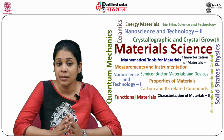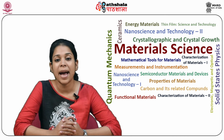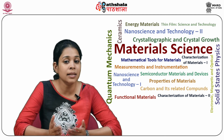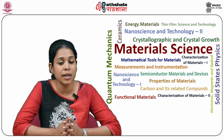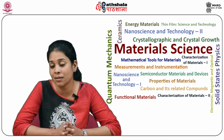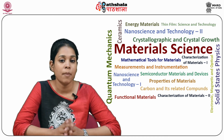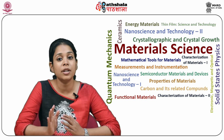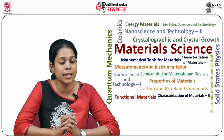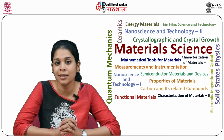We have discussed that earlier in the intro also, that soft ferrites like manganese zinc, that is MnZn, and nickel zinc, that is NiZn ferrites, are used as core materials in these applications like inductors and transformers in the frequencies ranging from 100 kilohertz to 100 megahertz, and typically these ferrites have high electrical resistance, which results in very low eddy current losses.